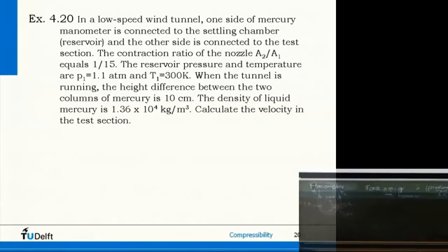Now, the thing is at rest, so if we look at this height, we have an equal force pushing here as pushing here. So the forces on the left side are P1 A, balance of forces. On the right side we have P2 A pushing, plus the force of this column, so plus rho g h times A. Now you see, indeed, the area of the tube, the area of the manometer, is not so interesting, so it drops out.